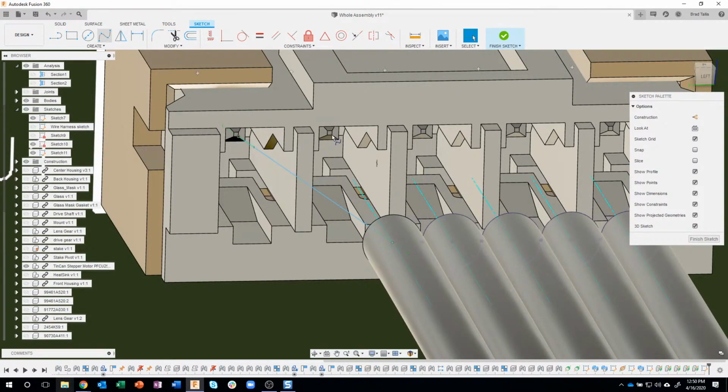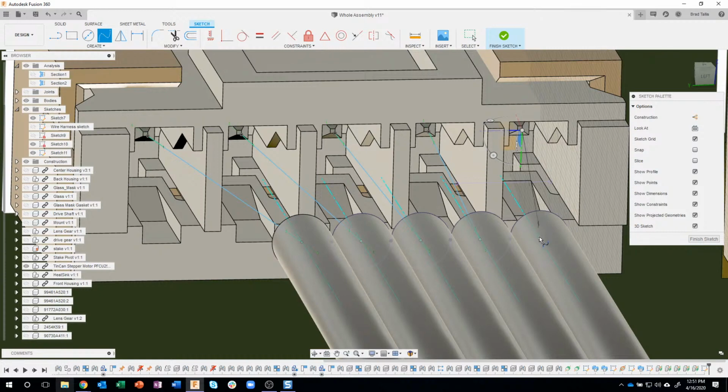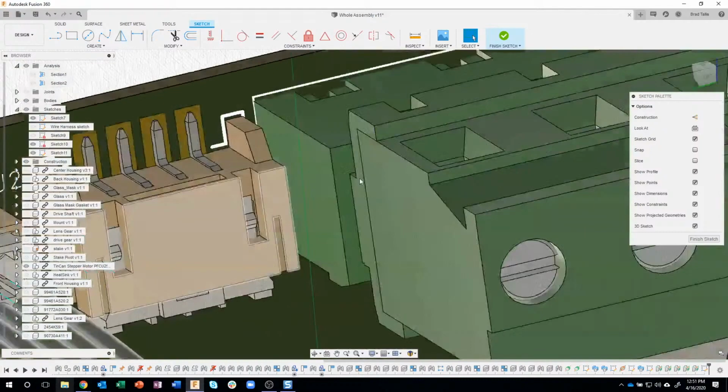And I'm just going to do this a couple times. Like I said, kind of repetitive, but hopefully you'll see what I'm doing here. So get near, making sure I'm catching to that box, and I'll say that guy, spline. And again, the key point here is to use the spline command, because that's going to give me the ability to change my tangency, direction, and weight. Okay, so I've just created those 5 wires.